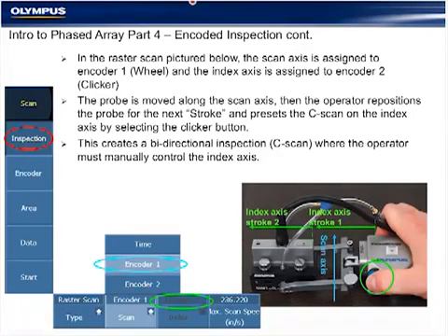So no matter what we do, after configuration of the UT and phased array, we configure the encoder or scanner to record the data. If we tell the software the orientation and position of the probe and configure our area and C-scan correctly, our data will accurately represent what's intended for the inspection.